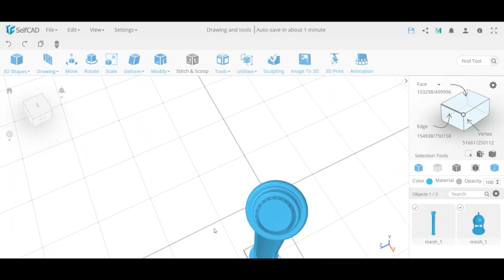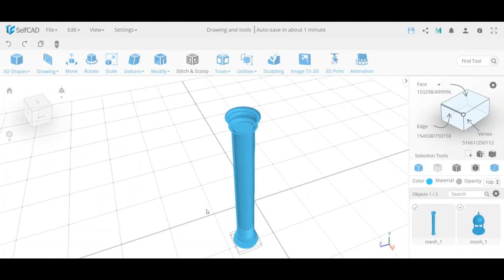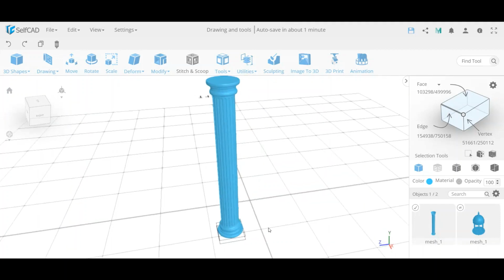I'm not sure exactly, but why is this working? What is backface culling doing? If I turn off my backface culling, you see everything. So let me explain what this is doing, and this is what the normals are doing, because we're actually going to use this later in the lesson as well, and that's something very important.